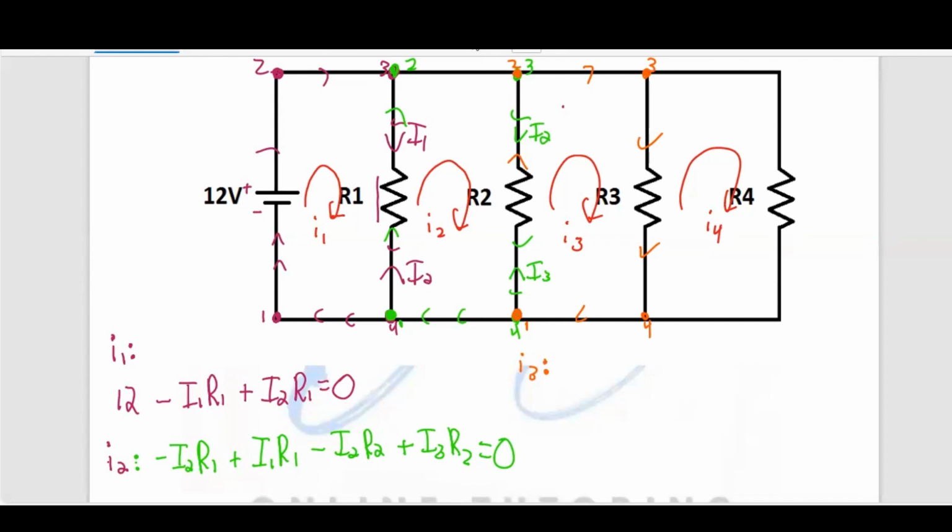Same, you notice 2 currents. You have I2 coming down and I3 going up. So anything that I3 goes through will be negative, so it'll be minus I3 R2. Anything going in the opposite of what we assume through the resistor will be positive, so it'll be plus I2 R2. If you notice, it's literally the opposite of what you had here for that part, because in this one, anything negative, in this one, negative. That's swapping it. But it's the same concept.